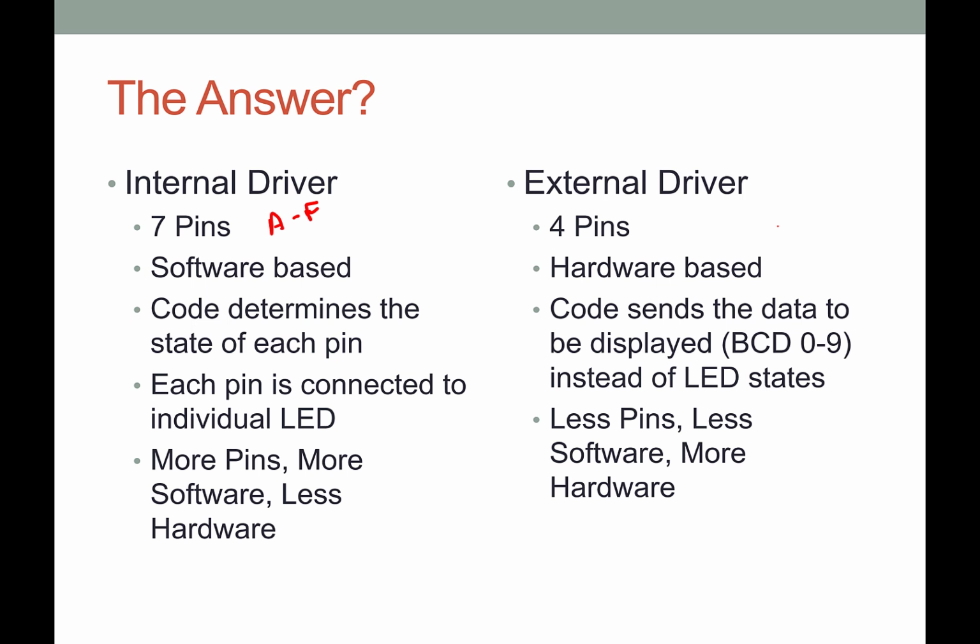7-segment displays that you have, like for example, if you think of a clock radio, well, you need a digit for the hour, a digit for the minutes, a digit for the tens of the hours, and a digit for tens of the minutes. So you need 4 digits, plus obviously you need something for the colon, and so forth. So you need a lot of pins to be able to control all of that, which gets rather expensive because creating external pins is rather tough. So we could do it rather than using an internal driver, we could use an external driver.